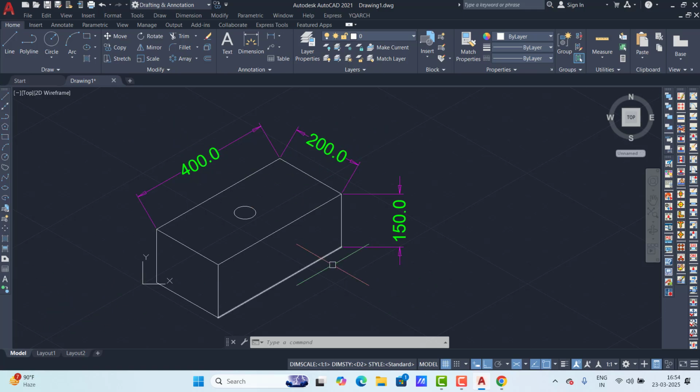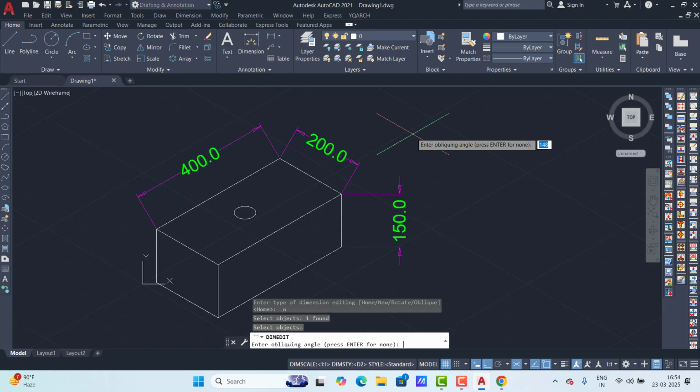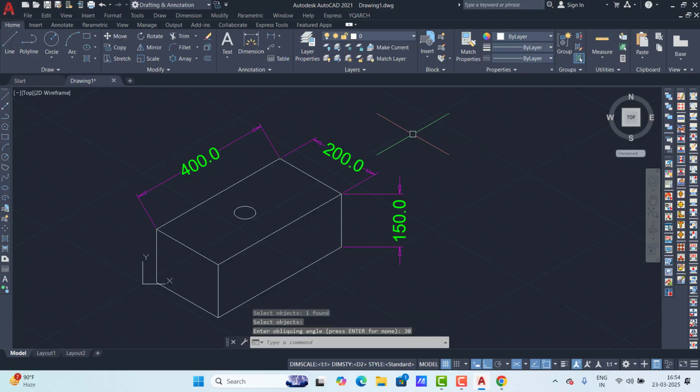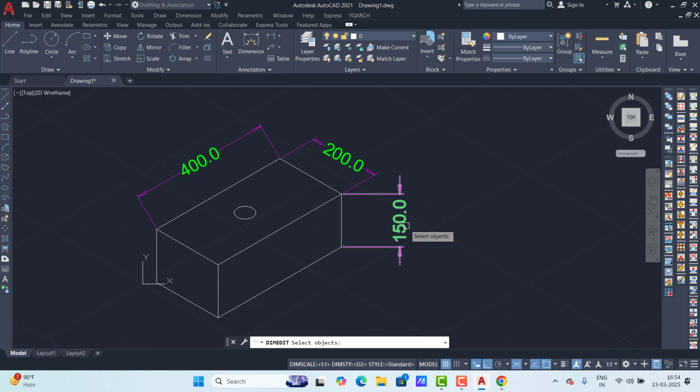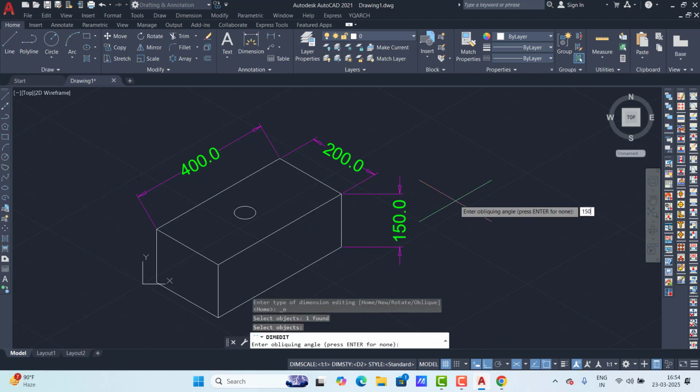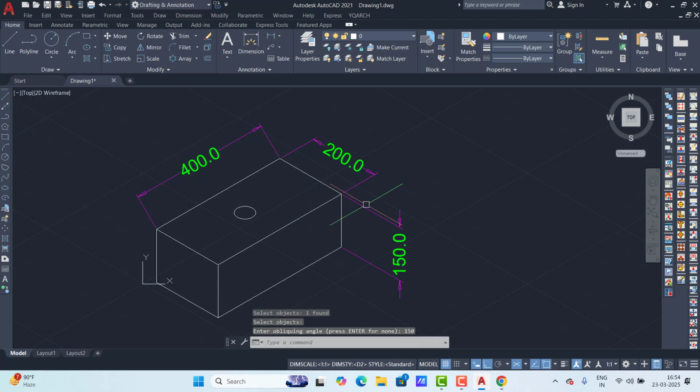That is the four circle holes. Radius is 4 and quantity 3, 3, 8 coming. Okay. Now this outer circle radius 29 and that pitch circle radius is 15.7. This one and this one are the same. So what we do? We make first this main center. Okay. Here the orientation is 34 this side, 34 this side. So what we do? Offset 34 this side,